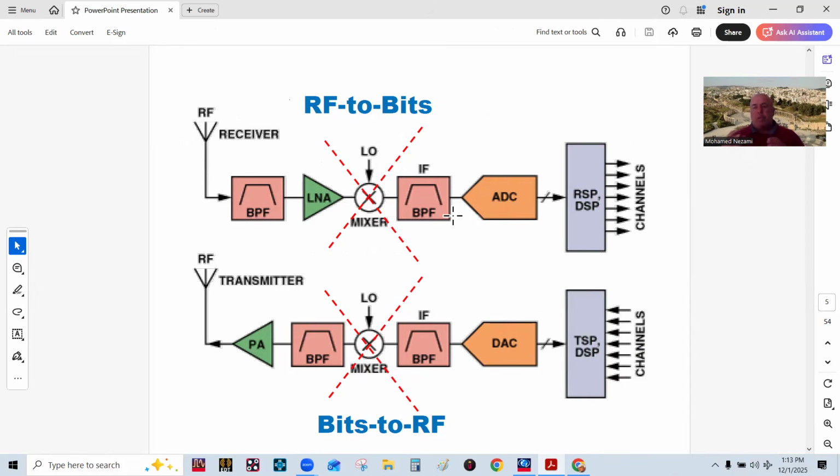Now, whether you digitize the baseband, bring it down to zero IF like direct conversion receivers, or high IF, in which you digitize it using an ADC, or you subsample it, meaning this IF could be either baseband, in the first Nyquist zone, or in the higher Nyquist zones, in which case we are doing subsampling.